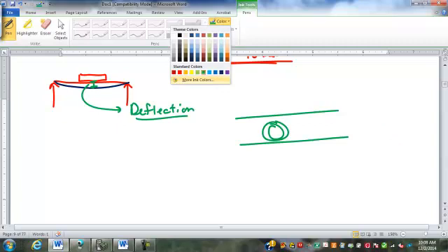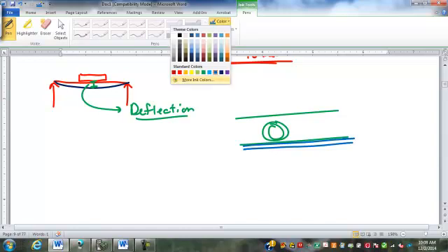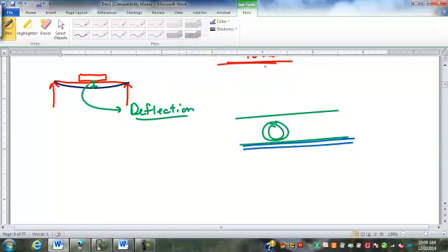Also, if you have a finished floor beneath it, if you have sheetrock or plaster on the ceiling below that, you can't have a whole lot of deflection, or that sheetrock's going to crack all the pieces on you. And it's going to be really horrible looking. So because of that, we limit the deflection beyond what would be required as a limit for structural integrity.